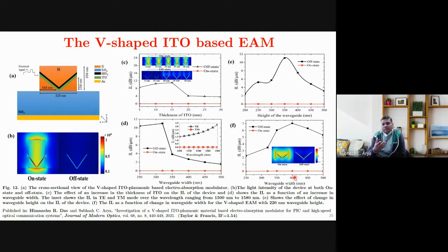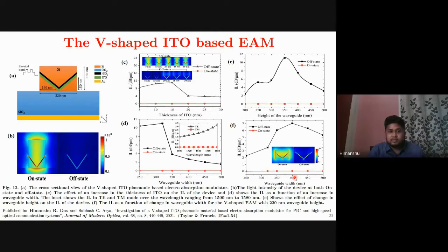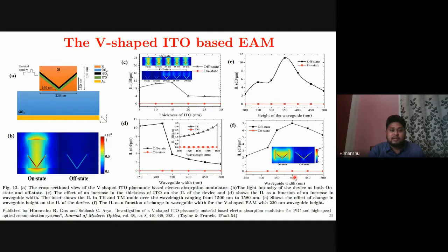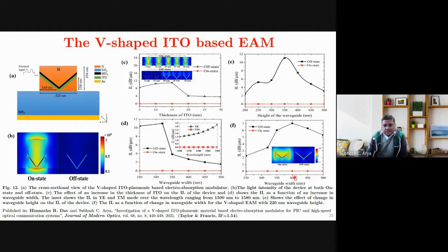But what is the peculiarity about 220 nanometer? From where does this figure come? Because in the current technology, the couplers we are using are of 220 nanometer. And what about 350 nanometer? The 350 nanometer devices we are designing, but for 350 nanometer the couplers are not available, which means we have to design that coupler. Okay, go ahead.